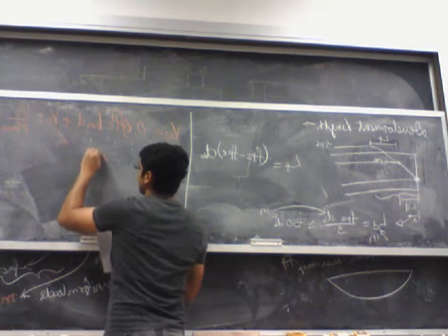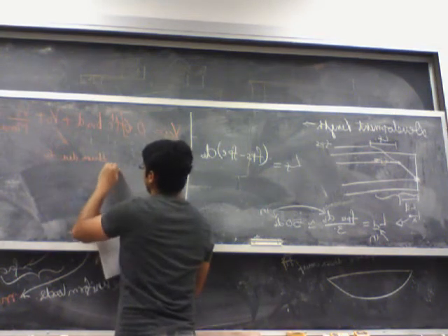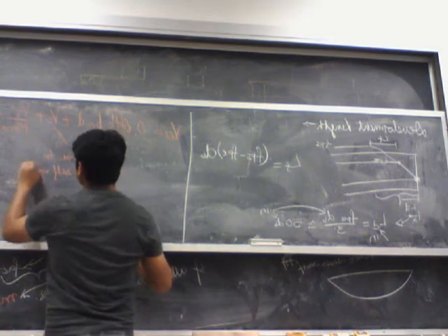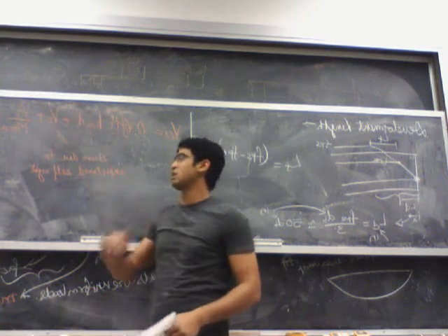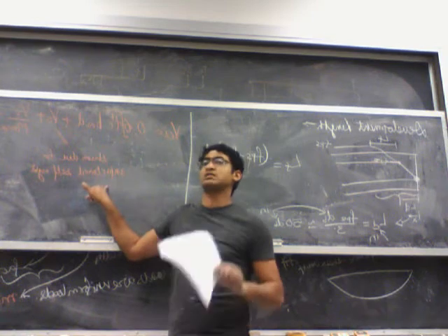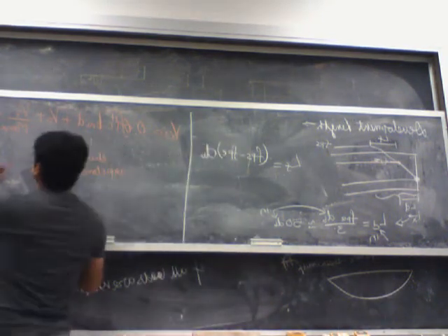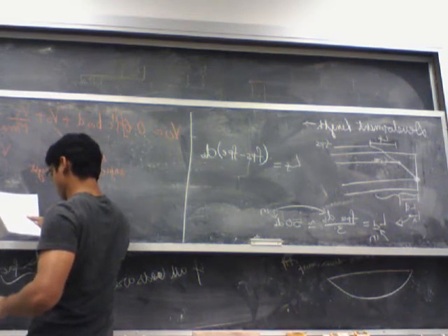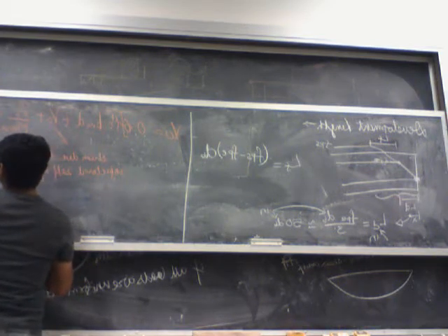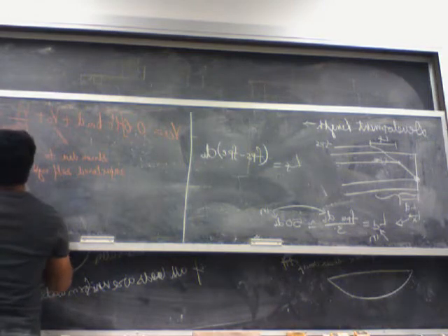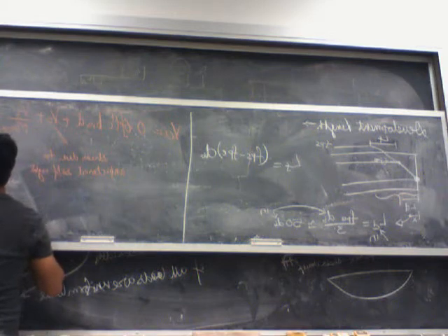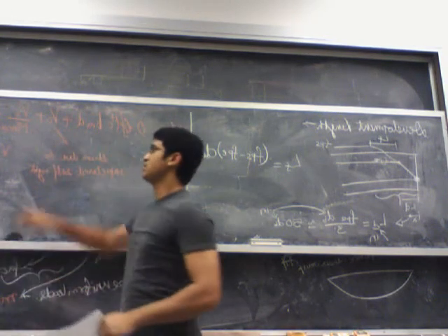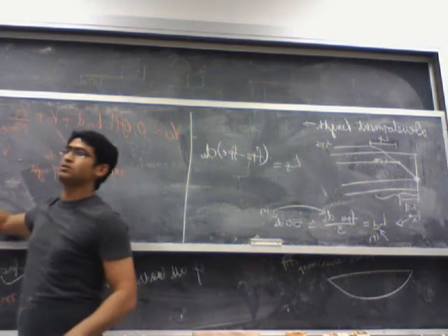V_o is the shear at that particular cross section due to the self weight, which is unfactored. So you will simply use omega_o to find out this value of V_o. And V_i is the shear at that particular cross section due to the factored loads except the self weight itself.